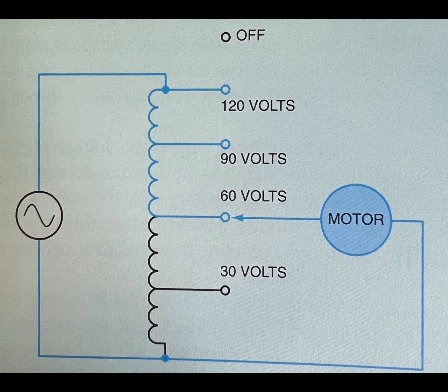Induction motors that use a centrifugal switch cannot be used with variable voltage control. This limits the type of induction motors that can be used to shaded pole motors or capacitor-start capacitor-run motors.